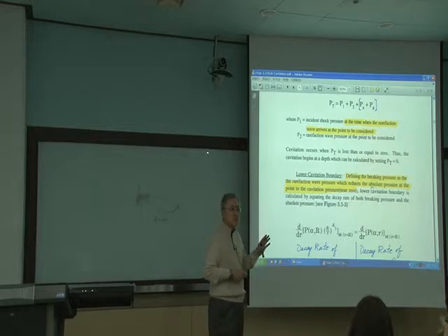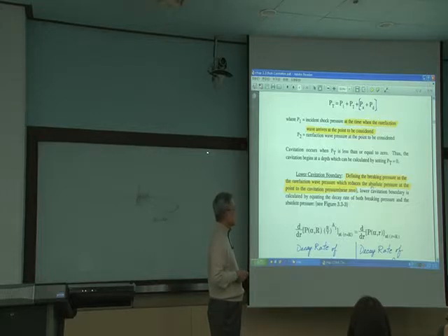Forget about the few negative psi, just assume 0. I'm going to read again. Defining the breaking pressure as the rarefaction wave pressure, a tension wave, which reduces the absolute pressure at the point to the cavitation pressure, which is near equal to 0.